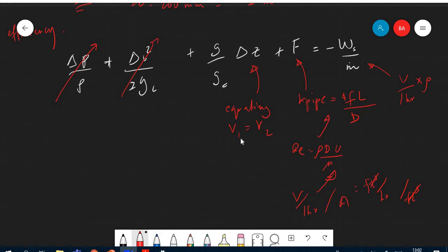So one by one I'm going to get delta Z, and then I'm going to get K pipe. Of course, if I need to get this F, I need the Reynolds number, and I forgot I also need E over D, the roughness factor. So if I get this, I can get that, and to get this U, I need this information here, substitute U, get Reynolds, E over D, get F, and if I get F, I can get K pipe, and that's good, right?